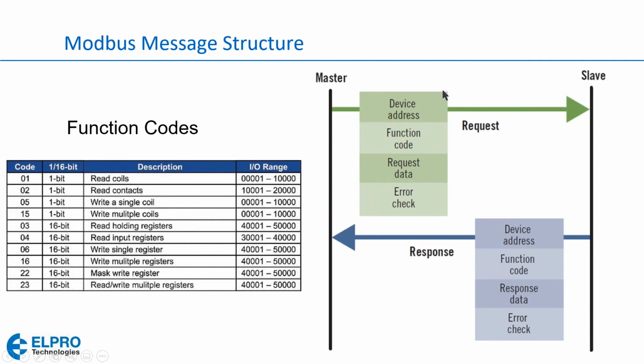I forget exactly how long these are, but these are going to be maybe 10 or 15 bytes of data. So extremely small packets, very low bandwidth requirements. The responses can be much larger. I think the maximum response size is limited to something like 512 bytes of data. But we're talking about bytes of data, not kilobits or megabits or anything like that. So the throughput you require on a radio system that is transmitting Modbus is very, very low.